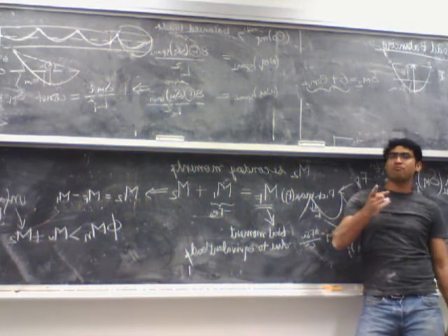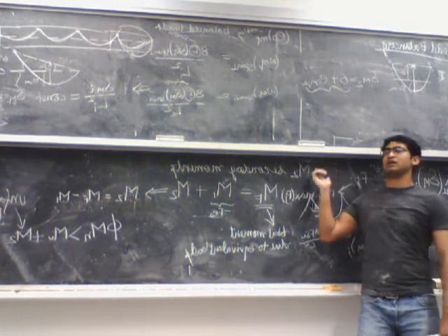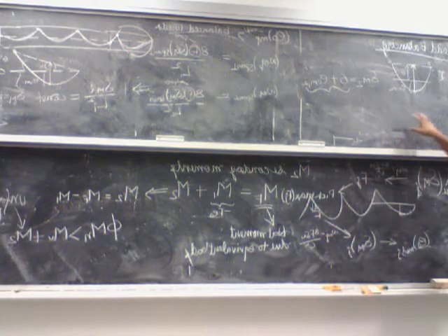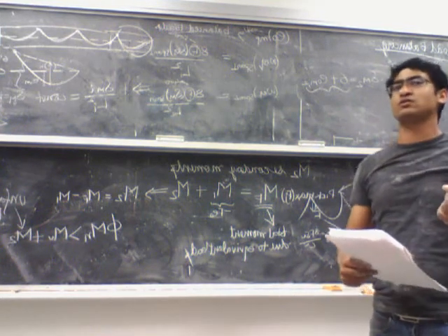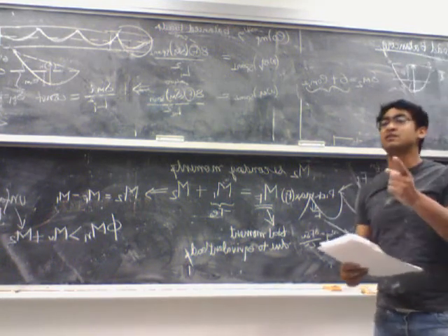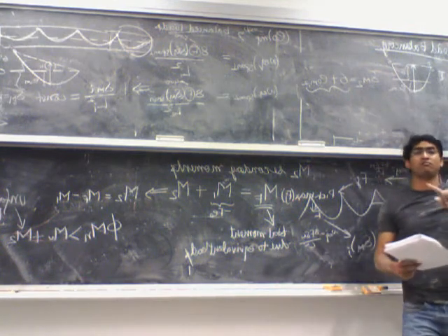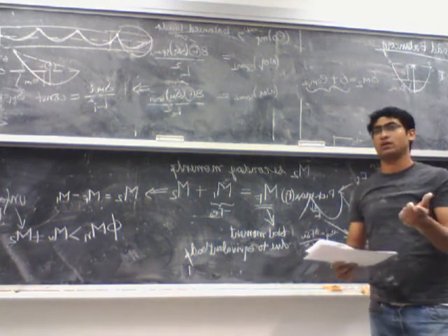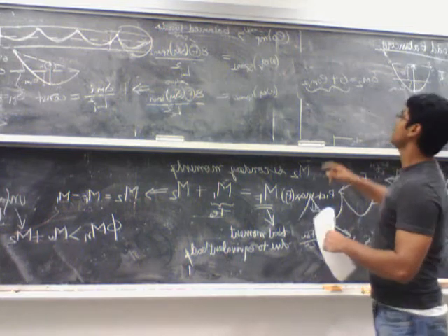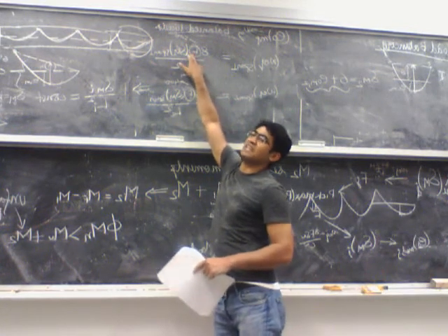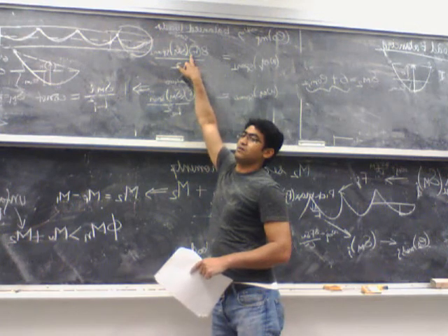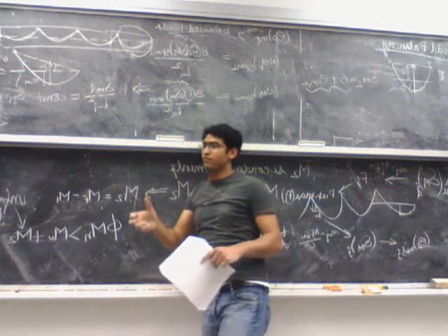And in the exam, be careful because it might say that the load which is balanced, let's say it says 90% of the load is balanced by the initial pre-stressing force, or it can say 90% of the dead load is balanced by the effective pre-stressing force. Then what it simply means is, in this formula, in the first case this is actually Fi, in the second case it's actually F. So read the problem statement carefully.